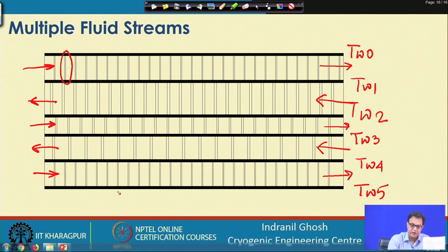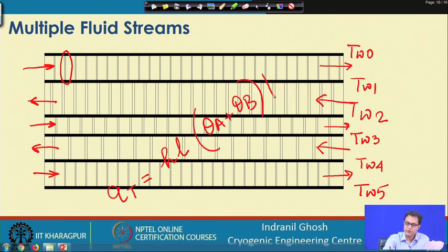So, if we now try to find out the heat transfer taking place through one single fin, that is what exactly we have told, that this is the Q T amount of heat getting transferred, and that was given as we have estimated it earlier, that it would come as H into L into theta A plus theta B and tan hyperbolic eta of fin half. So, as if half of the fin is attached to this plate and half of the fin is attached to this plate, and as if there is a kind of adiabatic temperature profile condition prevailing at the fin middle.